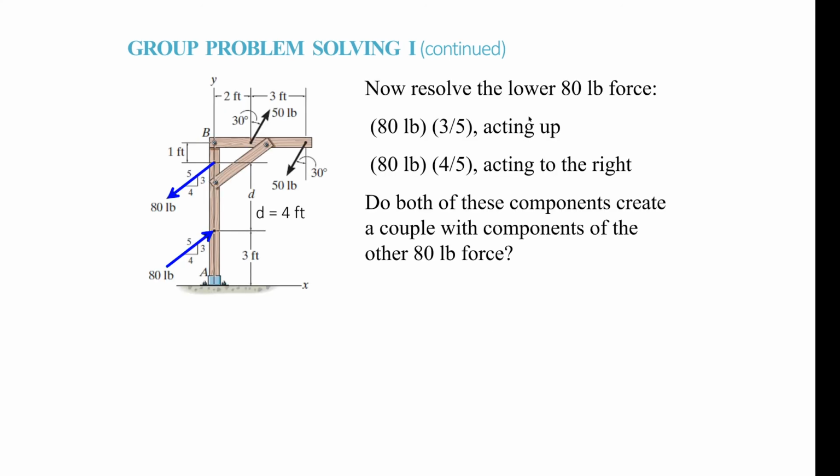Okay. This one, define it as being acting up. Well, thinking about the force that's acting up, the component of the force that's acting up, the component of the force that's acting down. And now if you notice that this component is acting right along this line, the Y component and the Y component, this one's acting straight along this line. So the Y component doesn't do anything for this. It's only going to be the X component, which is this part of the force that creates a couple.